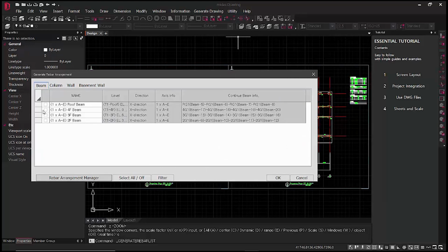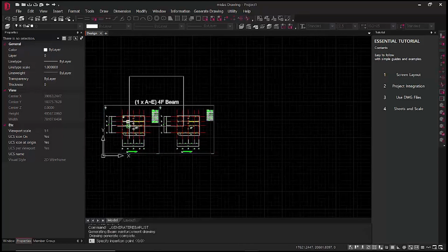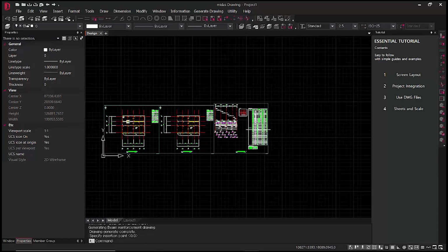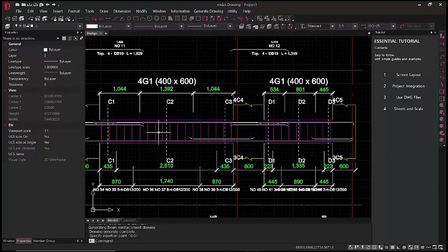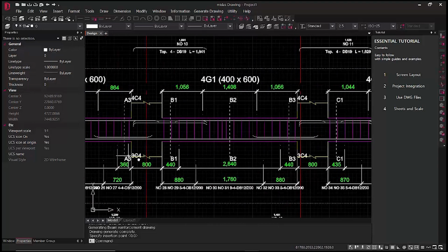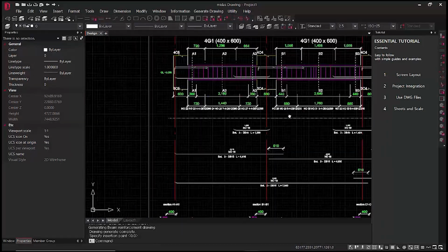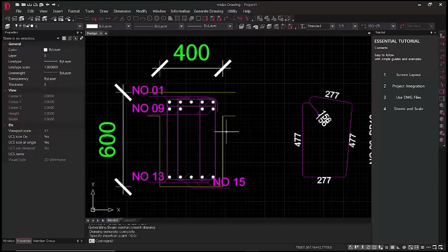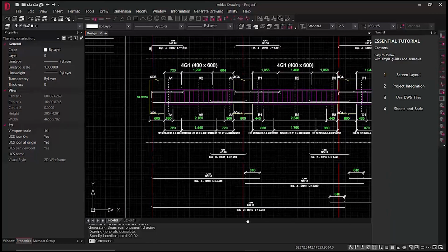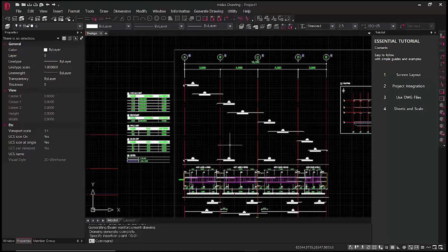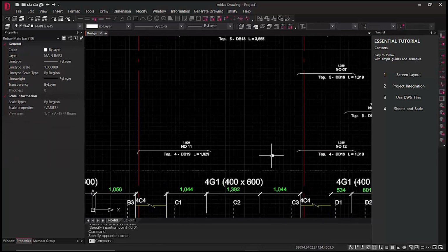Check on the longitudinal drawing of the beam member to be created and click the OK button. You can see that the negative bending moment area is set to 2 layers. If you select a lever, it can be linked to confirm the position of the member.